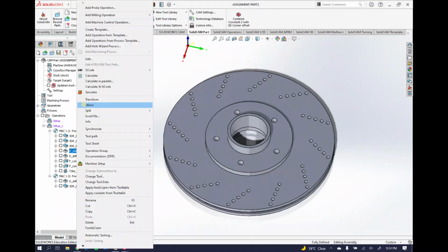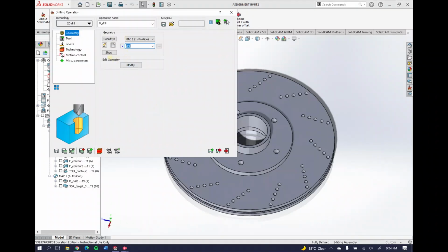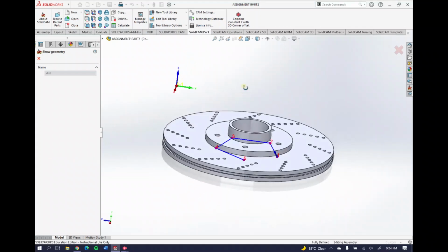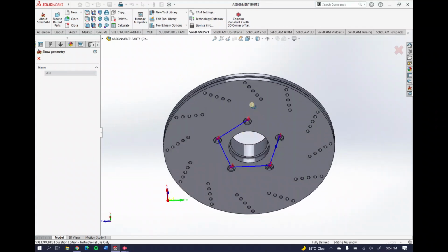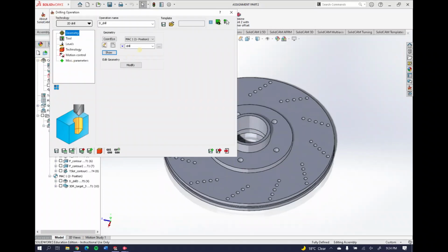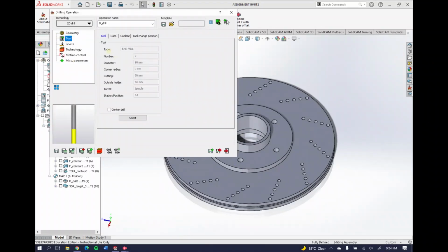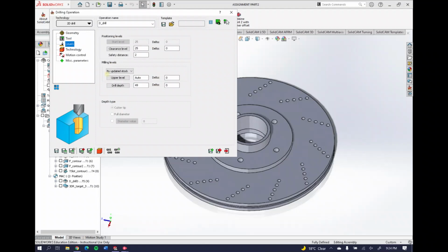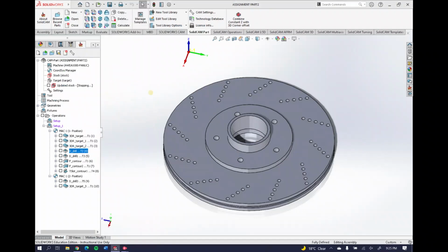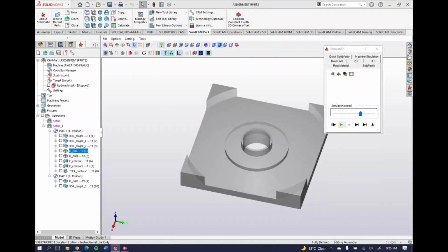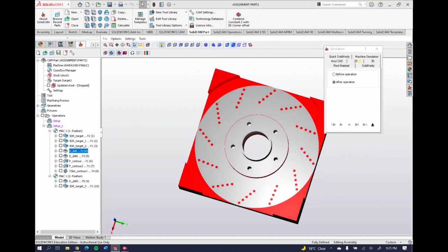Now for the drilling portion of this exercise, I just added that to show exactly what we did. I'll show you the working area. We just had to select our drill bits here, and that was basically it. We select our 10mm cutting tool, since that was the dimension specified on the drawing. The drill depth is 49, and we just left it automatic for that level. That will be all, and we'll simulate that to show you. As you can see here, that is what we end up with, and here's what we would have after the cut.